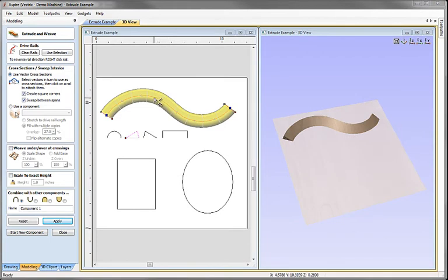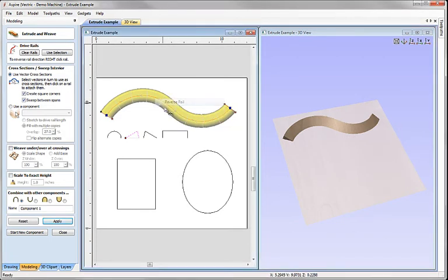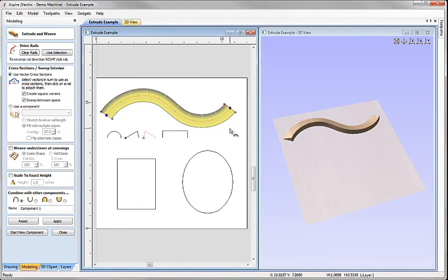Now let's right mouse click on here again, choose the option to reverse rail once more, and hit apply. Now I'm going to select this cross section, which is a mirrored version of this triangle here, and click to replace the cross section on this end with that one. So we can see the red node associated with this one, the yellow node here associated with this one.